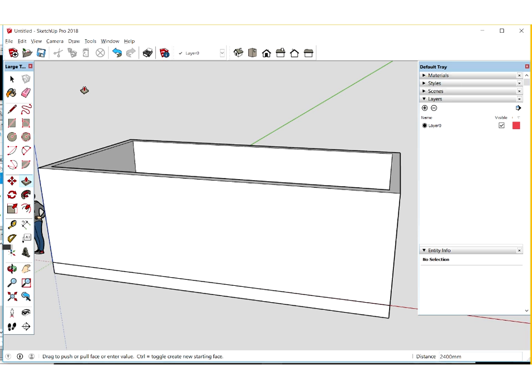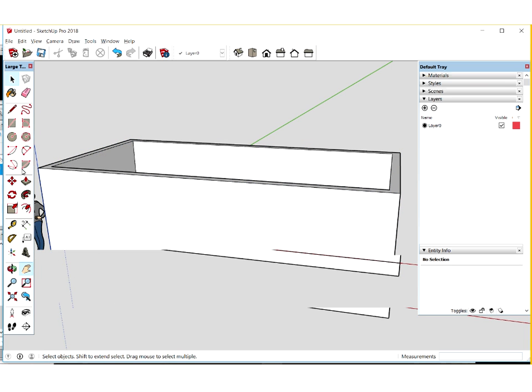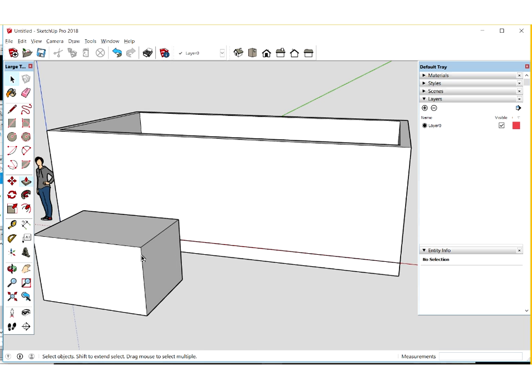So next we're going to triple click on our walls, right click and group them. So group them together and then put up a green tick. And for anyone who is new to the software, the reason why we do this is because SketchUp has sticky geometry. So for some people watching the workshop recording who may not have used the software before, anything we build in SketchUp will stick to the previous object if it's not grouped together.